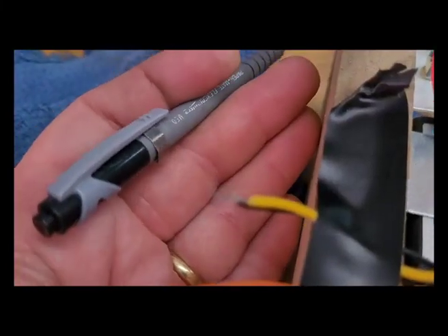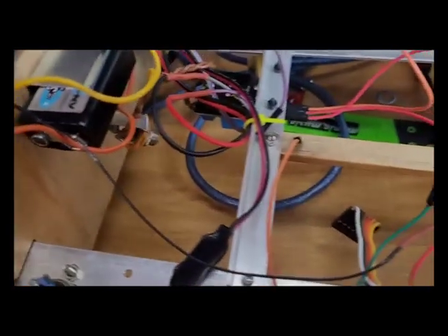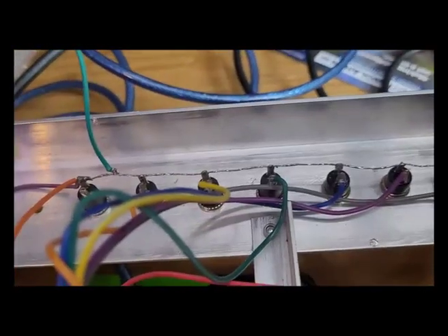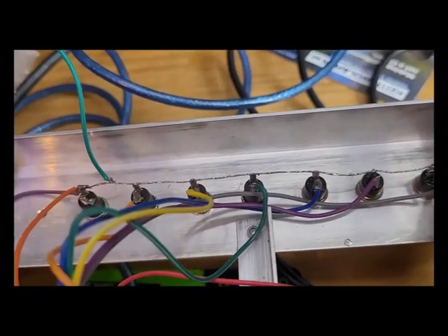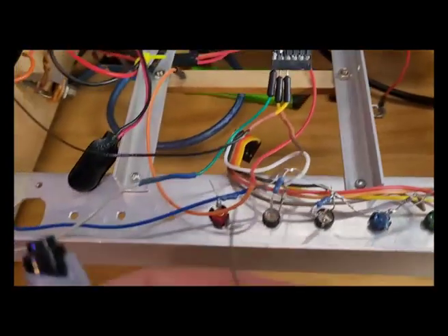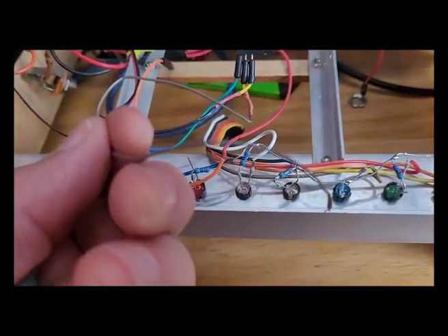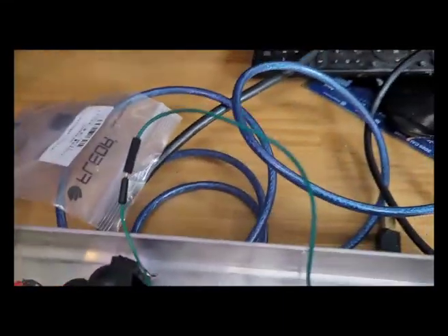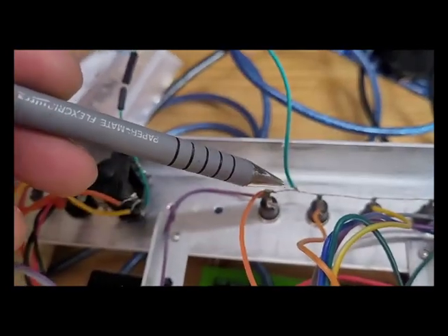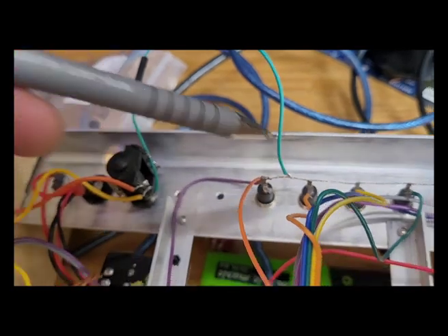The yellow wire similarly connects, I've just got them twisted together again, to the black wire, which is going to the blue wire. So the outside switch is in effect, it's unfortunate, it's a mess, but it's connecting these 2 outside connectors, and the purple wire in the middle is connecting to this brown wire, which we're not using right now because that'll be for testing tip and ring together. Also the first connector here is the sleeve connector, and that is just connected to the common unshielded earth or sleeve connector here.